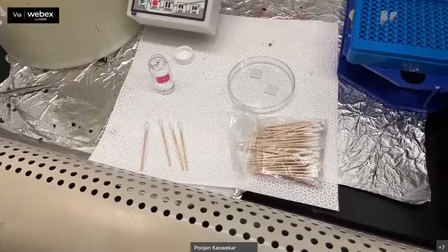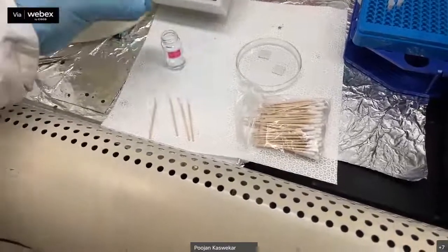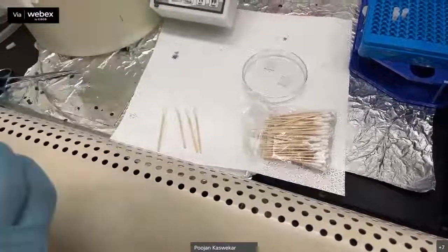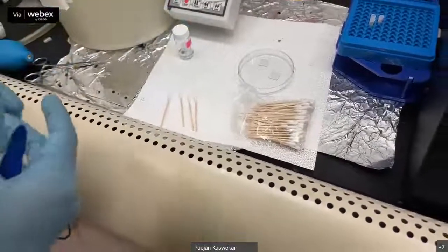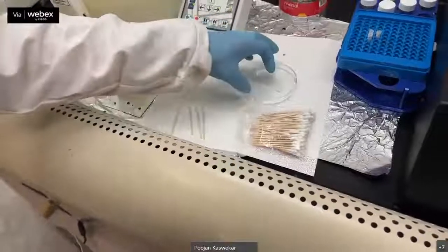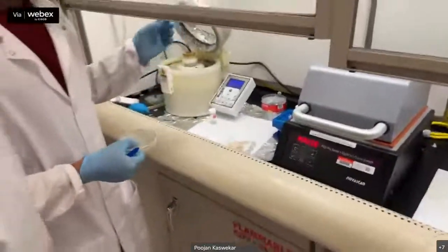If it is NIP, you are going to use SnO2 as the bottom layer, and the top layer is mesoporous TiO2. Since it's the PIN structure, we are using PEDOT:PSS to align the band gap. That is called band alignment.